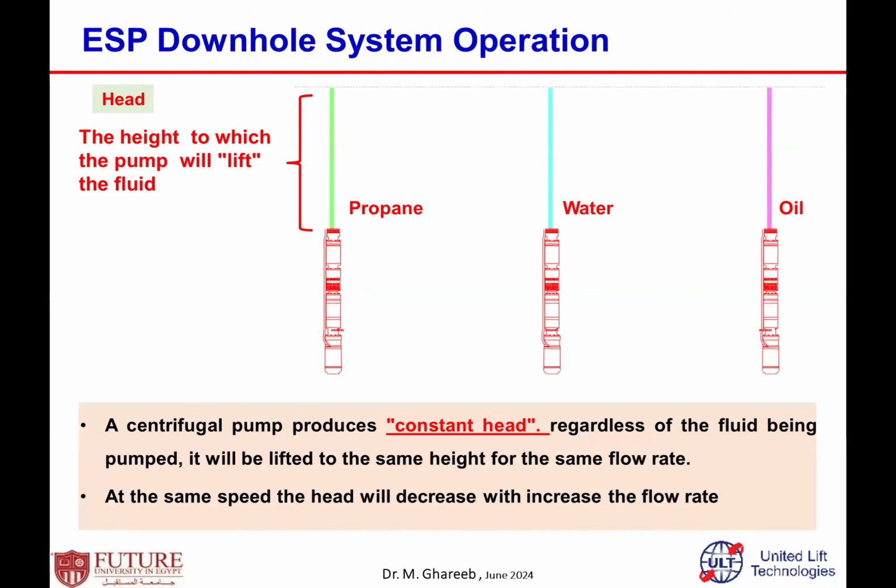For an ESP, since it's a centrifugal pump that depends on centrifugal force to convert the fluid from velocity to head, there is a general concept you have to keep in mind: a centrifugal pump produces constant head regardless of the fluid being pumped, because this is a function of the centrifugal force and velocity given, which is then transferred to the head.